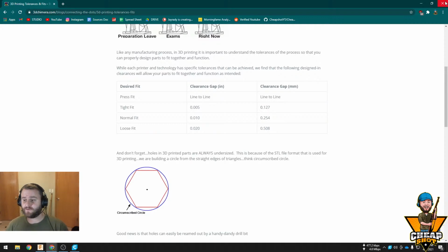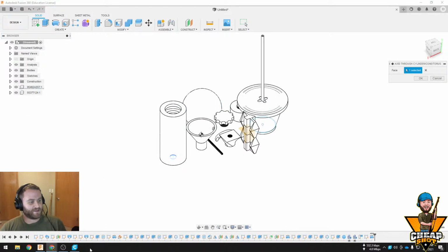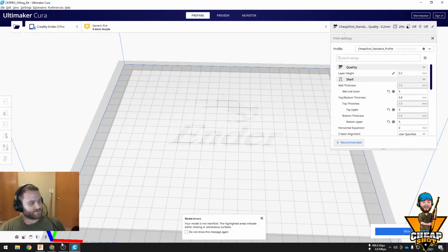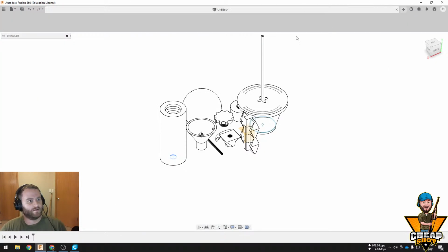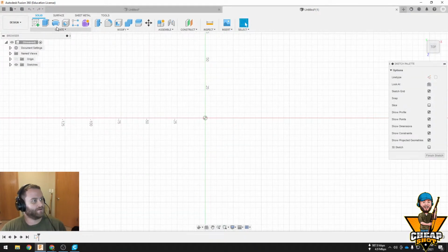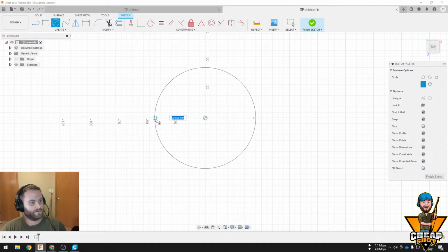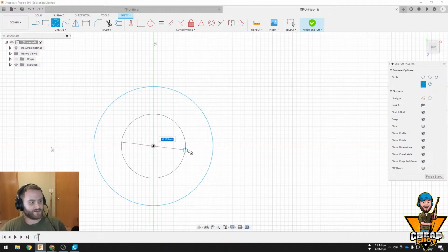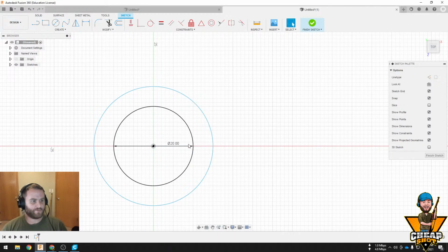But what you can do if you want to test this, Travis, is let's say I have a rod and I want to see what fits best on it. You can model your ring to go on it, and then import that same model. So let's do this. Let's say I have the ring, and I'm not going to go that big. Let's say 30. You have 2 options. I want it to be outside 30, inside 20.